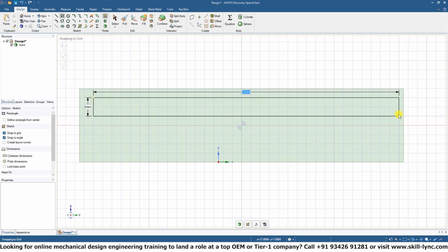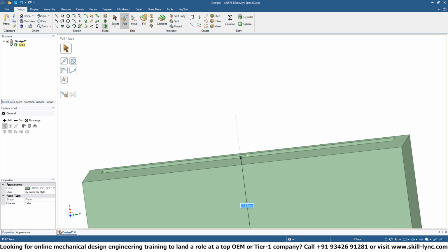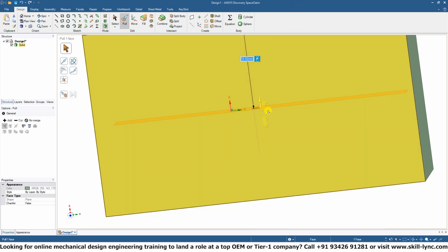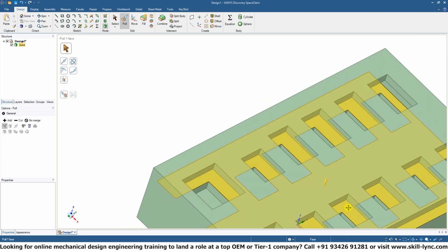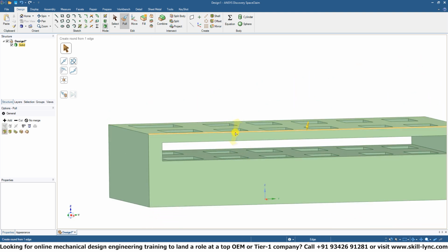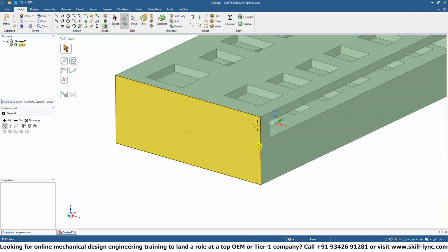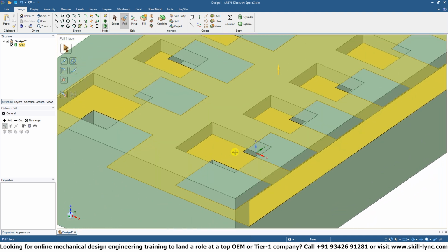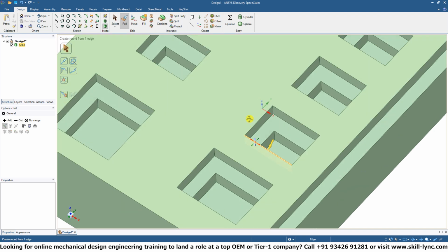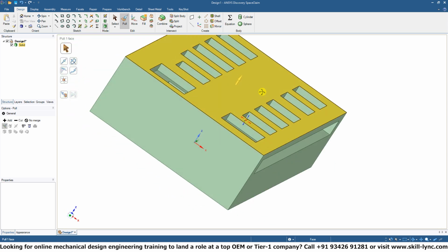If we create some reference geometry as in over here and negatively extrude this all the way to the other end, that will create a hole cut through the model. And as you can see, now we have a multi-layer model. So these holes went all the way through here, and we created another hole that goes through the side of the model. Those holes interact with each other. As such, you can create some interesting models or geometry in this way as well.